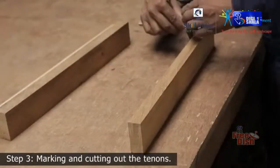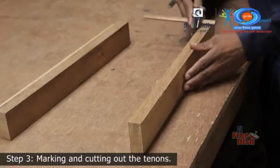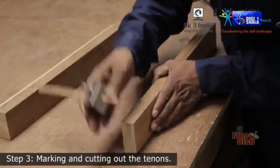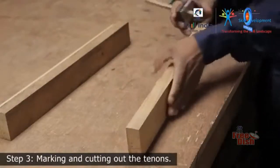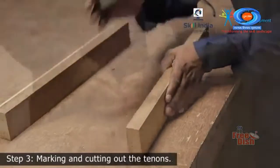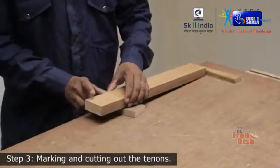Now adjust the mortise gauge and scribe a parallel line all around the edges for the thickness of the tenon. After marking, secure the member to the workbench and cut out the tenon with a saw.